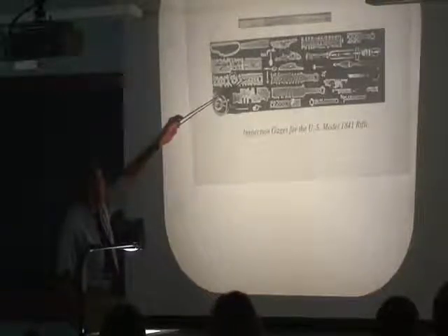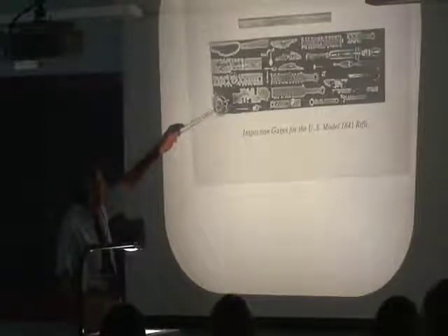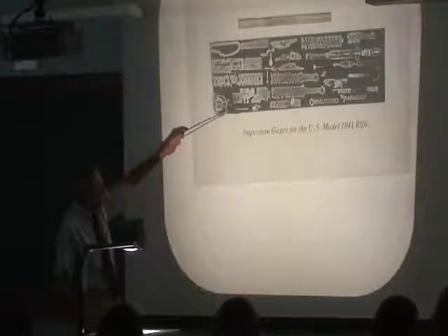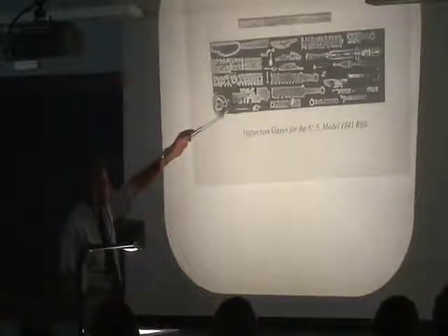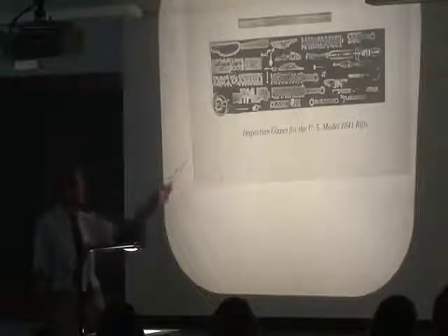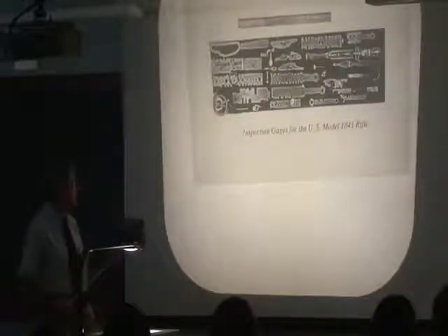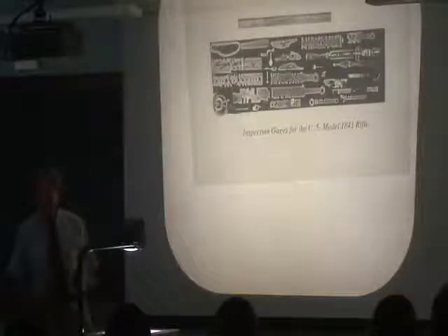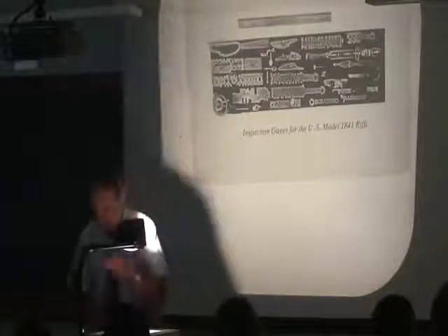Anyway, here you have a set of very fine, typically brass gauges with lots of little slots and things like that. Various parts of the rifle had to fit in some slots and not fit in other slots. These were go, no-go gauges. And the people making the parts had access to these things, and that was how they made them to sizes. And the people who devised the gauges did so to make sure the rifles would assemble interchangeably. The gauge makers were extremely clever people, and we still don't know what rules they used.